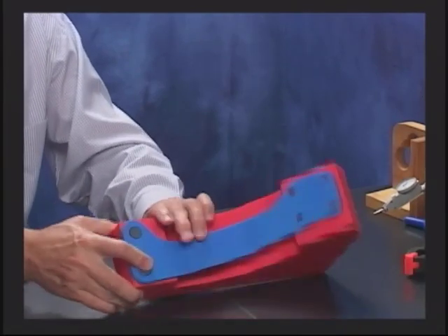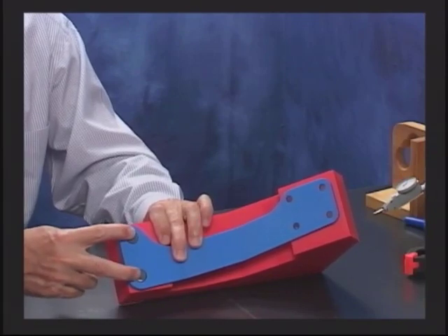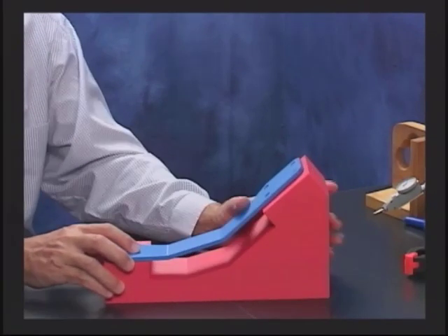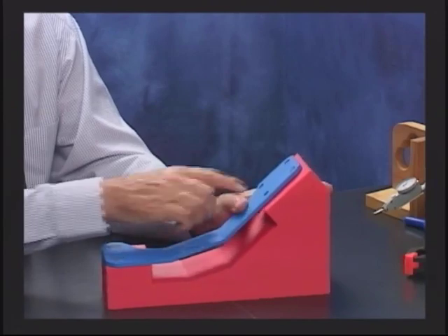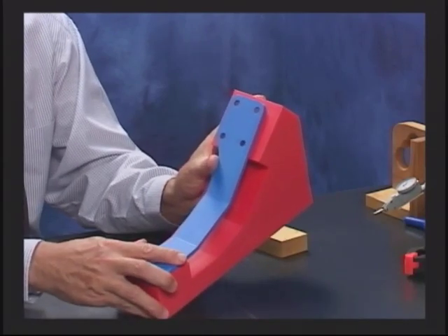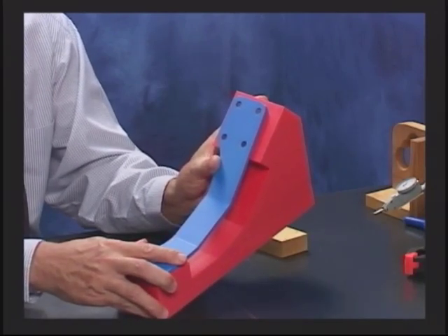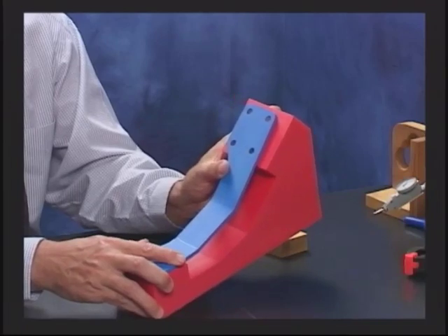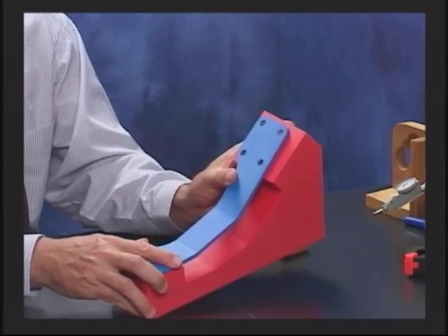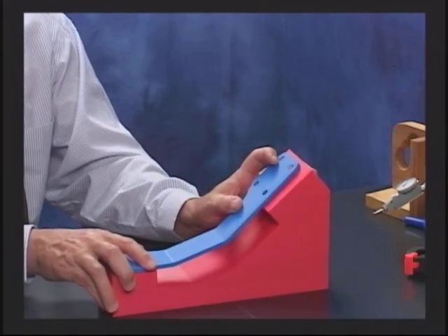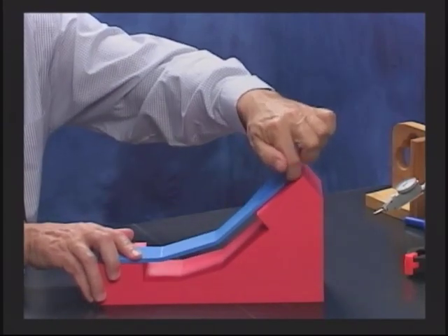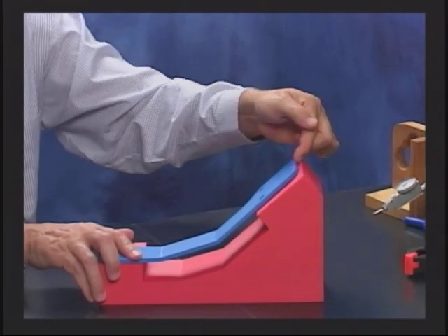It must accept these two pins. These are going to be virtual size pins. If they're virtual size pins, then over here, these are virtual size pins also. And the gauge pin size you should see in the workbook. It'll tell you what the size of the hole is, and you can see that they're 8 millimeter size pins. And then back here, this is going to be a feeler gauge check, that I'm going to come in and make sure that surface.